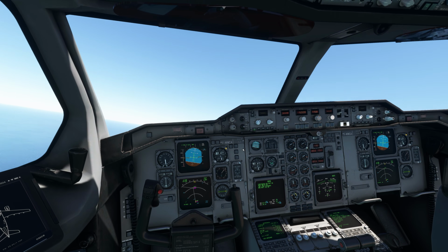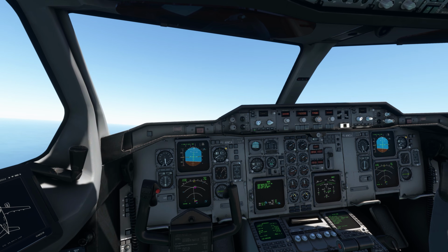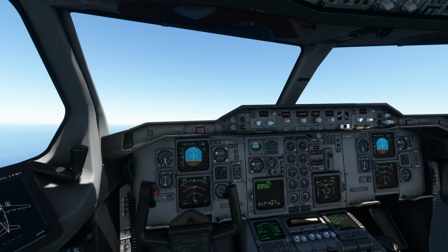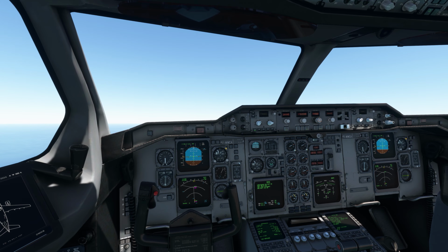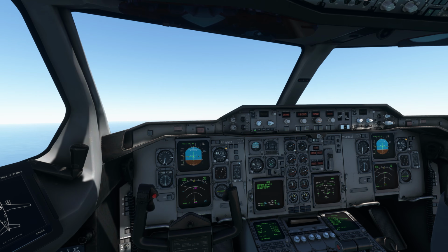Actually, the advantage of using profile mode is this, that you set your cruising altitude to 28,000 feet, you activate profile, and the plane should follow the constraints. But what I've seen is this, that this plane doesn't follow the constraints during the takeoff or during the landing. During the takeoff, I always use profile mode, but during the descent, I use the level change or the vertical speed mode, which I will definitely explain to you in this video.